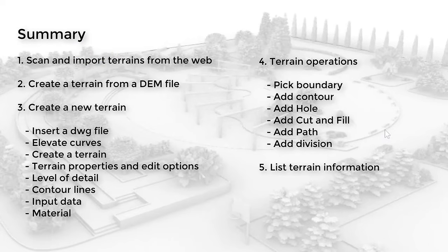Hello! In this video tutorial, we will cover all features of Lands Design for creating and modeling terrains. We will start by showing how to scan and import points from the web, as well as creating them from DEM files. Then we will start a new project, creating a new terrain from curves. We'll check its properties and options, such as the level of detail of the mesh, contour line display options, managing input data, or changing a terrain's material.